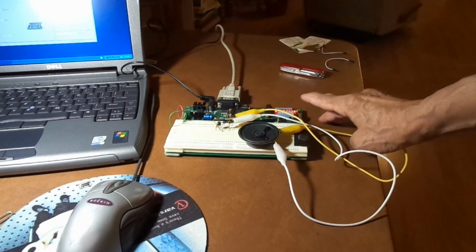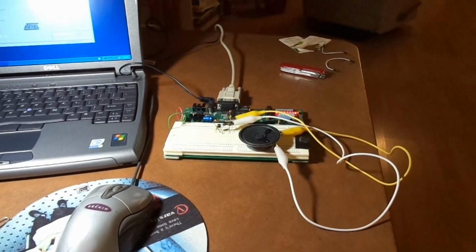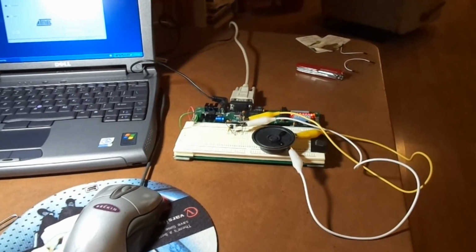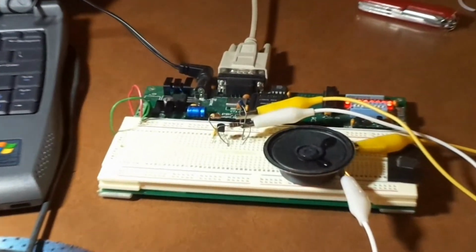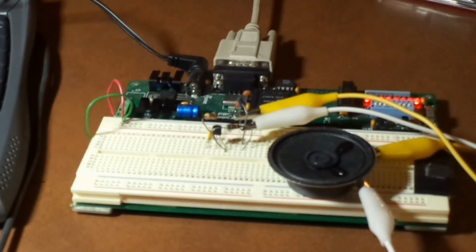Here is the circuit in operation using the original code, and if everything is working right, it should be putting out a sound, a frequency of 602 hertz. And then it'll be a challenge to reverse the calculation to see if I can put out a frequency of 1 kilohertz. In that case, you have to simply rearrange the formula to find out how many machine cycles we need, and so change the code.